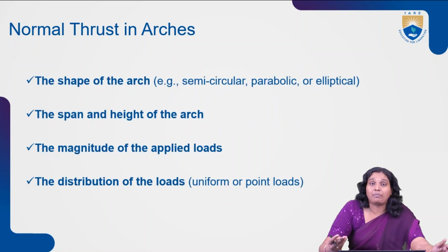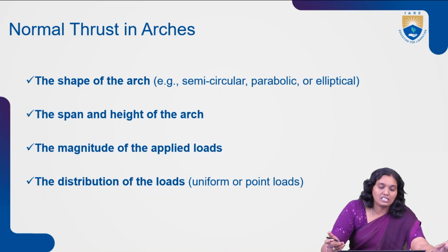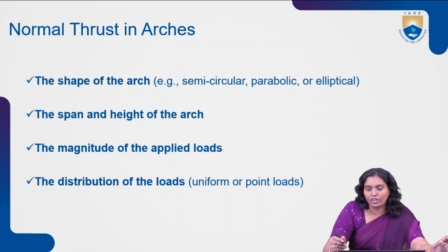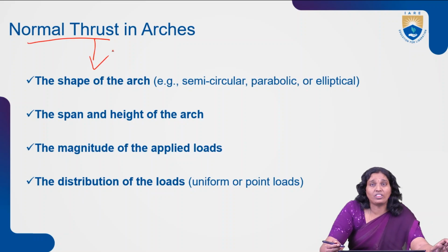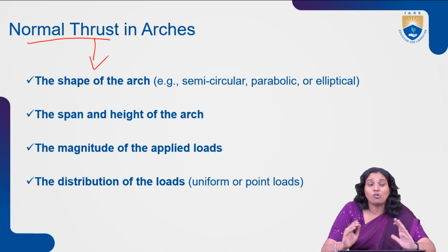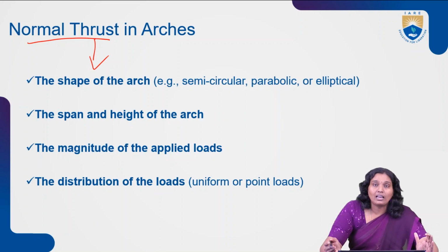The amount of normal thrust depends on several factors. It depends upon the shape of the arch, whether it is semicircular, parabolic, circular, elliptical, whatever it may be, and also how much the span is, since we use arches for longer spans, and the height of the arch and the magnitude of the applied loads.